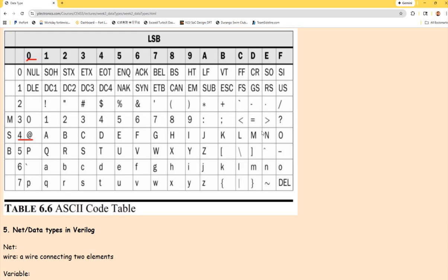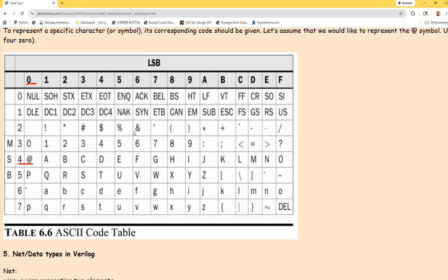So most of you did the microcontroller with me last semester, so we all know ASCII code, right? The ASCII code is from the keyboard, or especially for serial communication, when you are sending a character. It has its corresponding 8-bit or byte representation, and that's all the numbers you can find in the ASCII table. These are the LSBs of the ASCII code of the byte, and these are the MSBs.